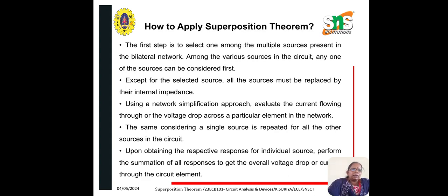So next we will see how to apply superposition theorem. The first step is to select any one of the multiple sources present in the network. Among the various sources, any one of the sources can be considered first. Except for the selected source, all the other sources must be replaced by their internal impedances.